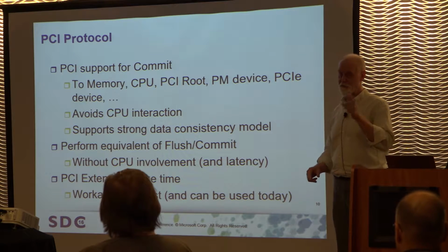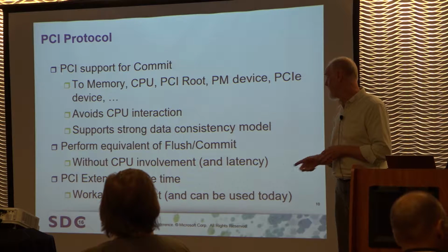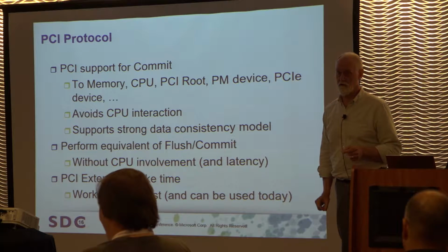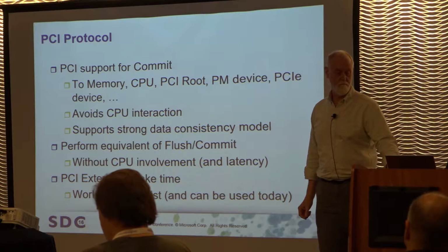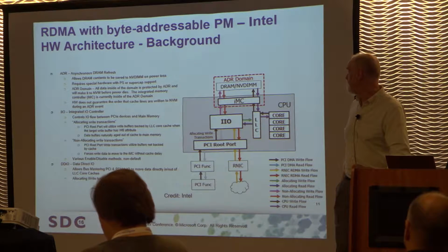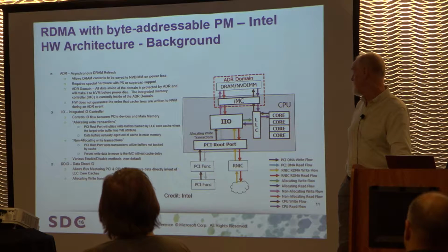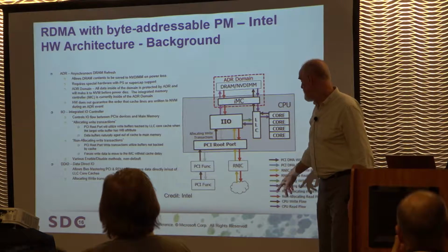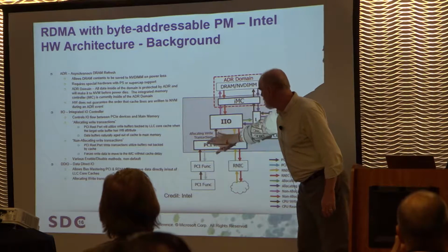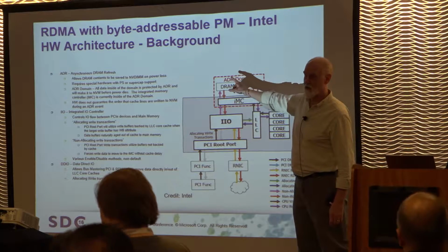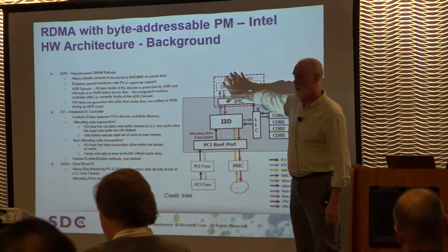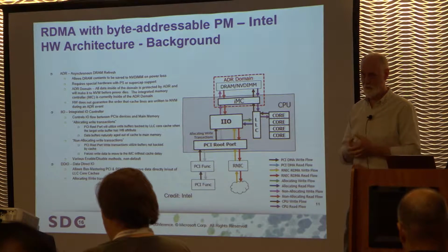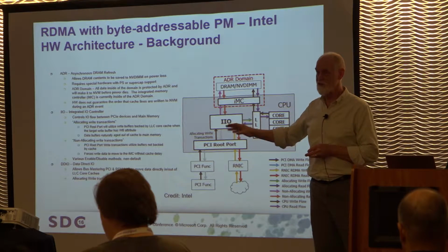And I'm going to mention a couple things from my friend Chet Douglas. The idea is to avoid CPU involvement, and the workarounds largely require CPU involvement. So this is one of Chet's diagrams that I swiped. It's about ADR, and it draws this little red box called the ADR domain. The idea is that you can form an operation that makes it into the ADR domain and is therefore persistent. ADR is a hardware domain, right? It requires a specific motherboard facility with a super cap or a special power supply or something. But it is a solution that's available today.